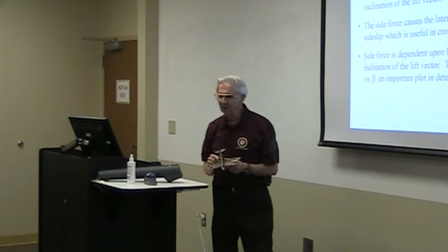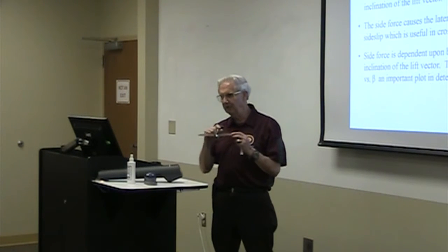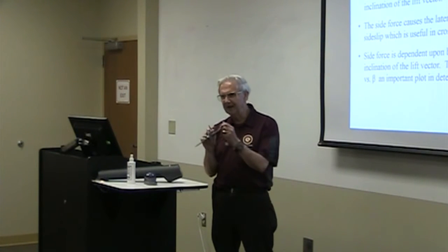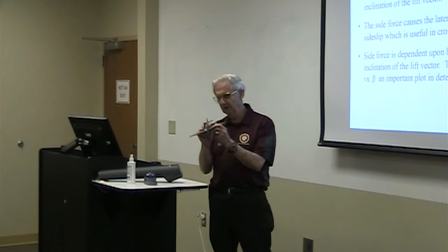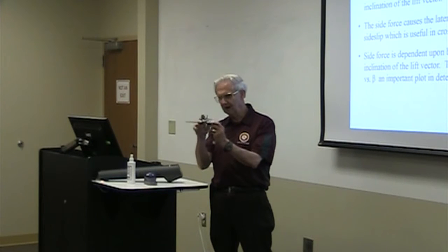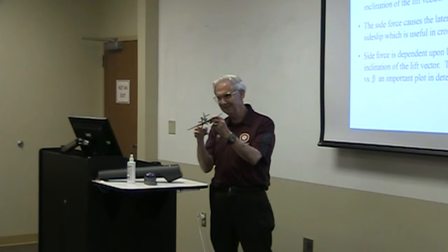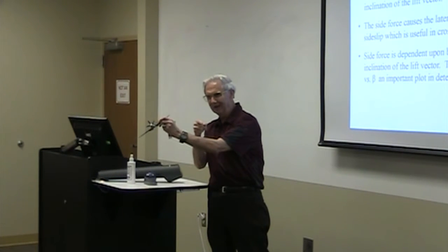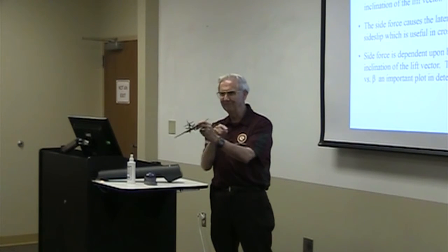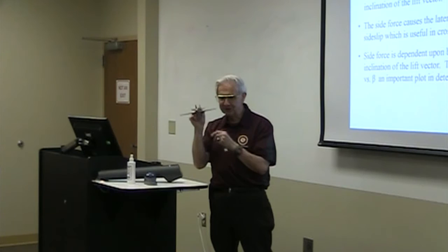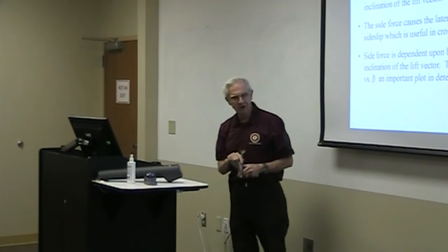We talked about that earlier. In the crosswind landing, we put the wing down into the wind, tilting that lift vector, and so if we took a piece of air at the time we did that, we're actually moving this way. Although, due to the fact that the wind's blowing at that velocity, we stay straight.